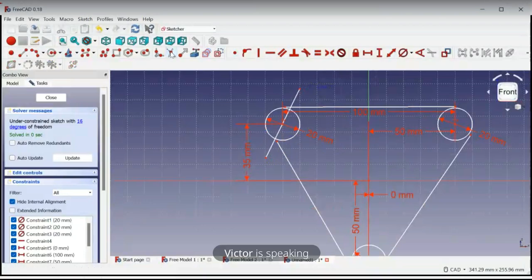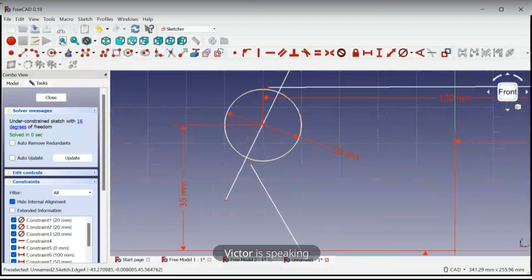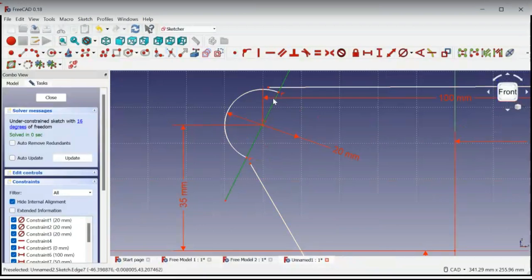After drawing this line, you want to cut off this part of the circle, so you can put your scissors and cut it off, so that you can connect these lines to this point and this line to this point. So now this line is no longer useful. You can click it and delete it. You only used it to cut off the unwanted part of the circle.